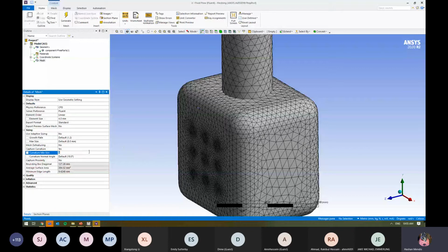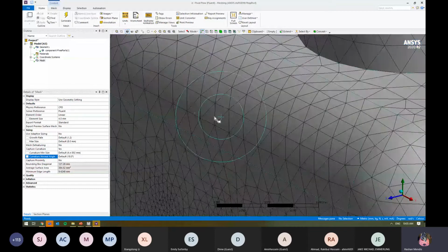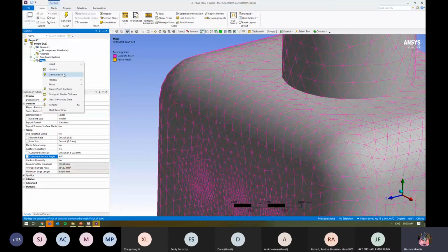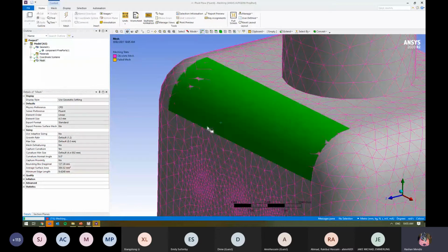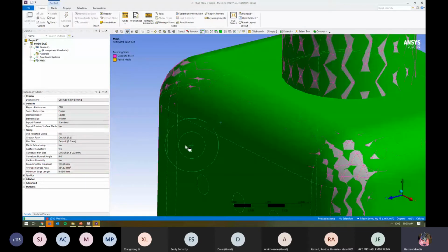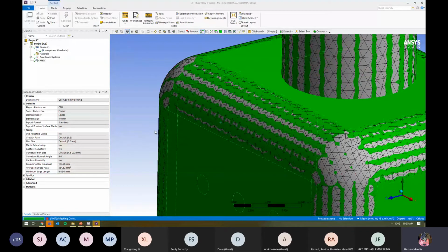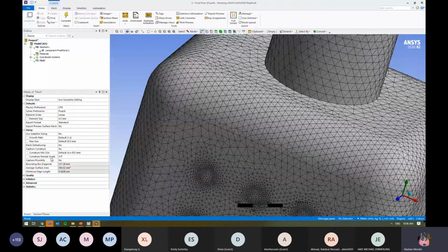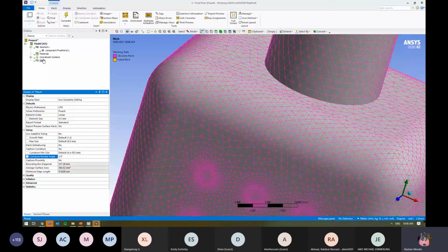At the moment, the minimum size is relatively small, and we've got a normal angle of around 18. What this normal angle is, I'll switch this over to 9 and generate that again. It'll try to determine what the angle is at which I can put an element. Sometimes the minimum sizing might be a bit smaller. You can see in this particular case, I didn't change the minimum sizing, but it's now able to put an element every X amount of degrees.